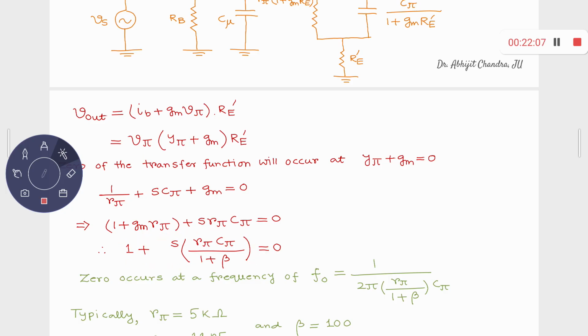Okay. So last time, hopefully you can remember, in our expression for the voltage gain, VOS upon VIS, you have something like some constant K divided by 1 plus S tau. That time I told you that this S parameter was there in the denominator, and there was nothing in the numerator. In the numerator you have a constant term, and in the denominator you have some S dependent term. So there were no zeros, you have only one pole. First order system, only one pole.